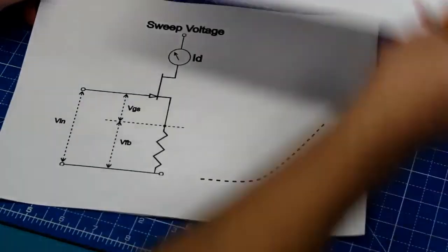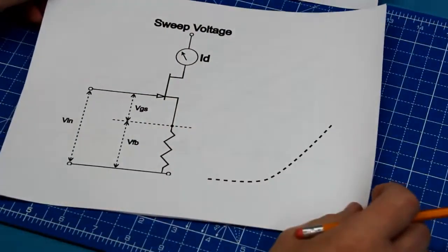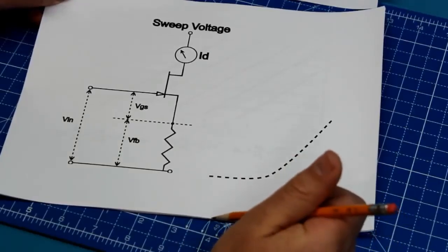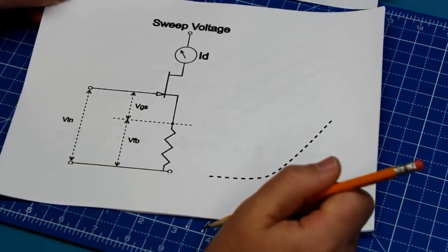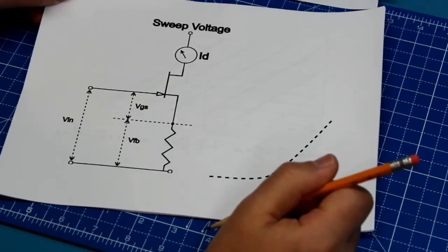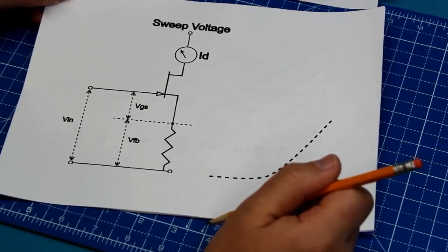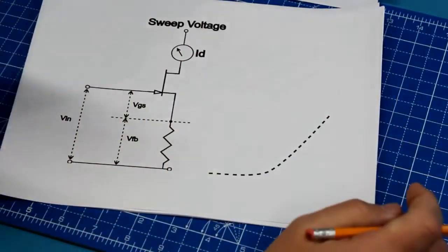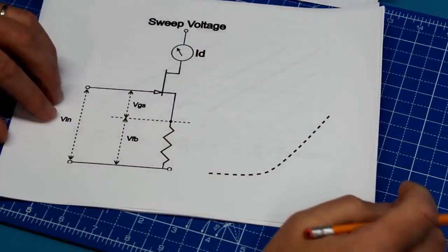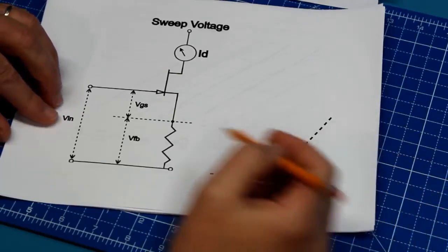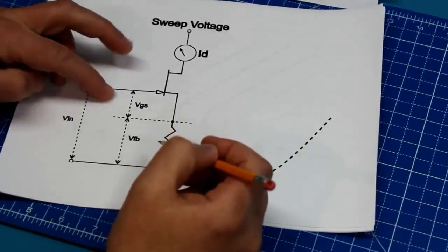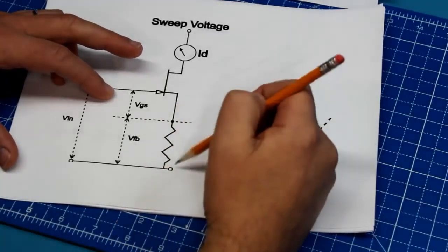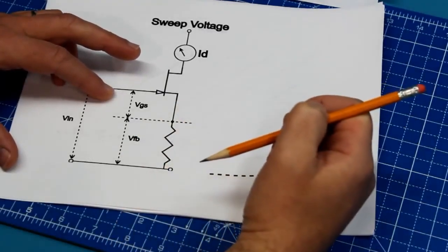What we're doing in the second part of the demonstration is we've inserted that 1 ohm resistor into the source of the transistor. And what's happening now is my curve tracer is putting out that constant voltage input, but some of that is being subtracted, so this is negative feedback from the input, because we're dropping some voltage across that 1 ohm resistor.